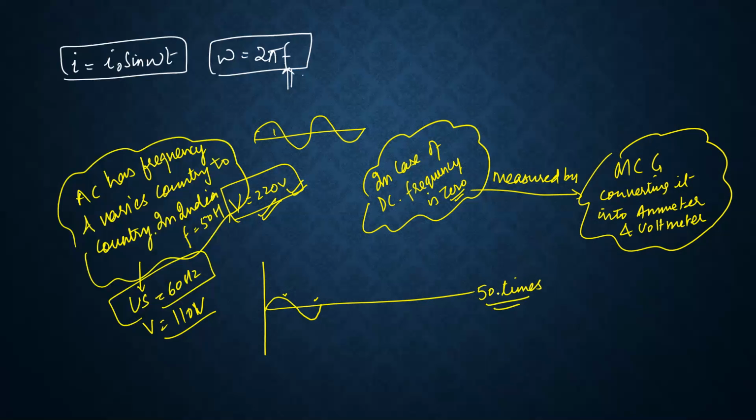That means अगर ये 50 times vary कर रही है in 1 second, what does it mean? कि आपको positive current और negative current, पहले पॉजिटिव फिर नेगेटिव, फिर पॉजिटिव फिर नेगेटिव, कितने टाइम्स? 100 टाइम्स मिलेगा वेरिएशन। और यहाँ पर देखो करंट आपका जीरो भी तो हो रहा है, और कितने बार जीरो हो रहा होगा? 100 टाइम्स जीरो हो रहा होगा, और 100 टाइम्स ही अपनी पीक वैल्यू अचीव कर रहा होगा.